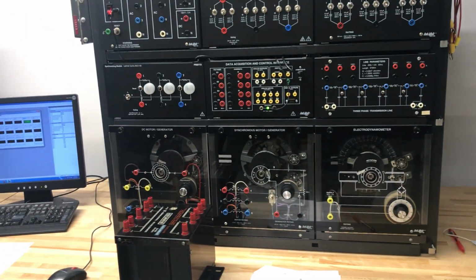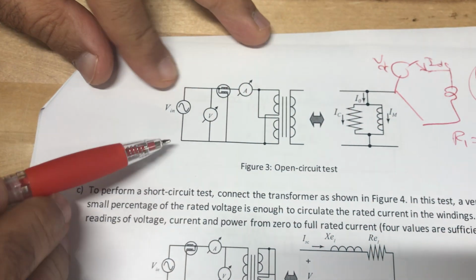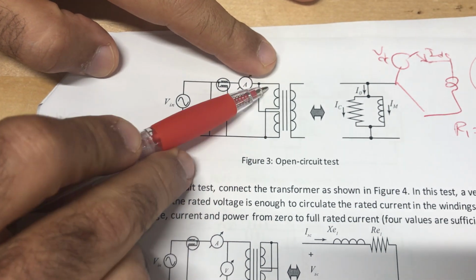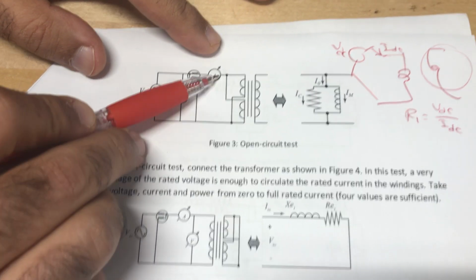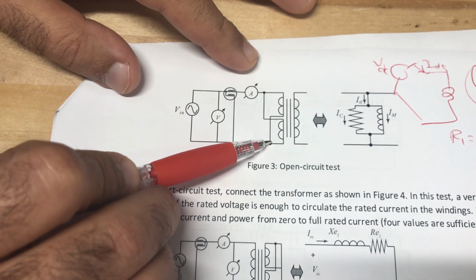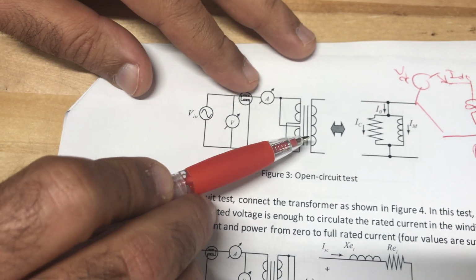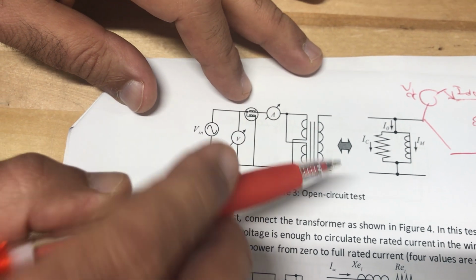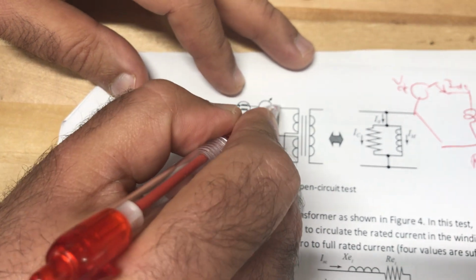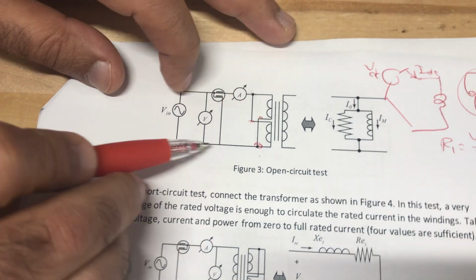So for the open circuit test, let us see the open circuit test circuit. So this is the open circuit test, and this will be the equivalent. So what we need is to connect the supply to here. He connected the supply to these two windings. And like what I mentioned during the class time, where should I put my measurements? I put them here in the secondary winding that has low voltage. So for the open circuit test, I open this guy, which is, in our case, we are considering it the primary, and we connected this point to this point, and this point to this point. So the start to the start and the end to the end.